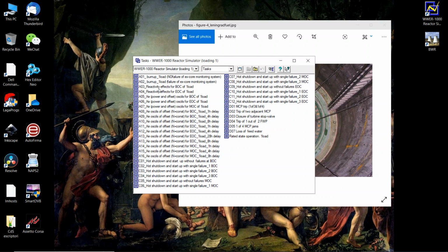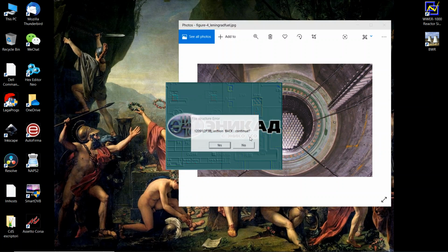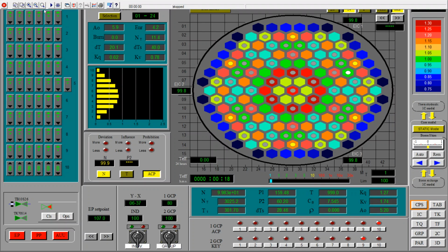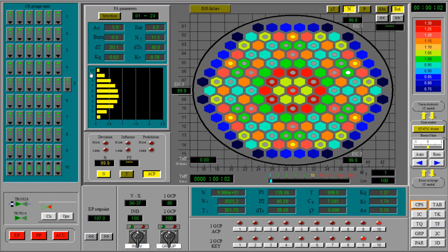We will start with just the normal 100% nominal power. Okay, start the simulation, and now my idea is to decrease primary pressure until we reach boiling. So I will monitor power and see the state of the group 10 auto control and see how the reactivity is affected.